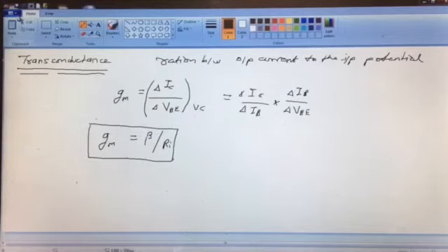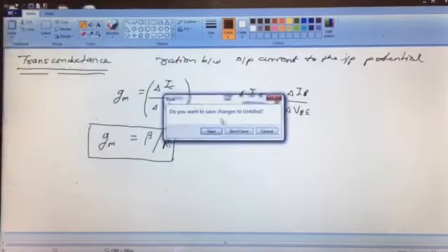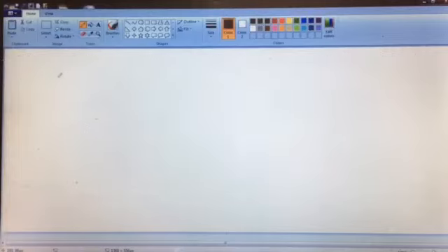Now leakage current. The next topic to compare is leakage current. The leakage current is due to the flow of minority charge carriers. As the minority charge carriers increase with temperature, the leakage current increases with temperature. The leakage current in common base configuration is very small.